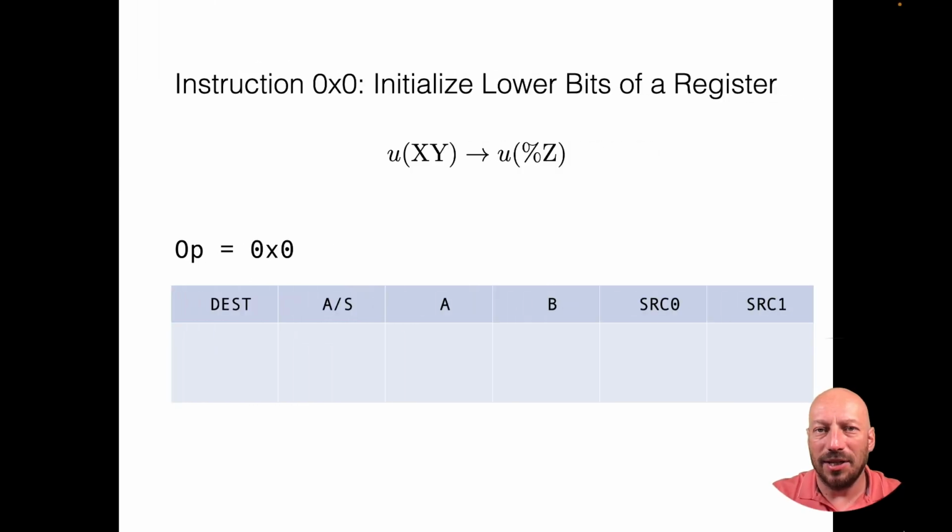We now finally can begin with the implementation of our instruction set, and you will see in the end we will have a table where the opcode gives us an index to the row. And that means this first operation with opcode 0 is the first row in this table. And each column of this table will be realized or implemented in Circuitverse with a multiplexer. And as I said before, I now just have to make sure that all operations can be represented as an addition or a subtraction, so that I can do the simplification in my ALU. And so that means I just rewrite it first like that. And then I just have to fill out the blanks.